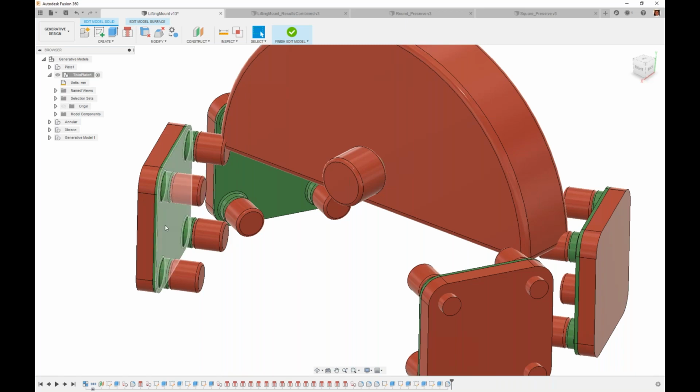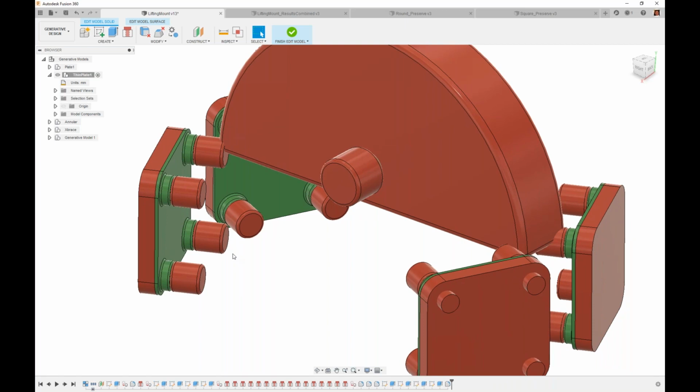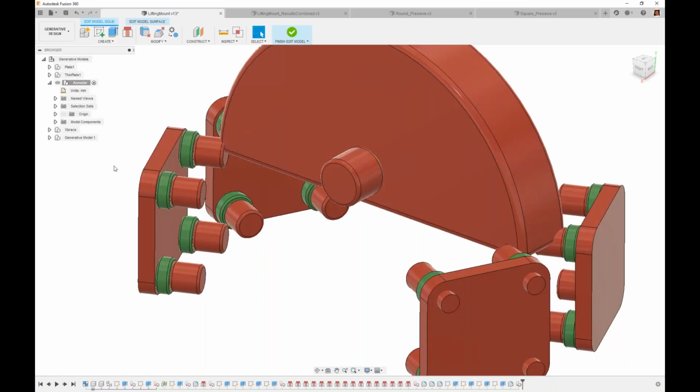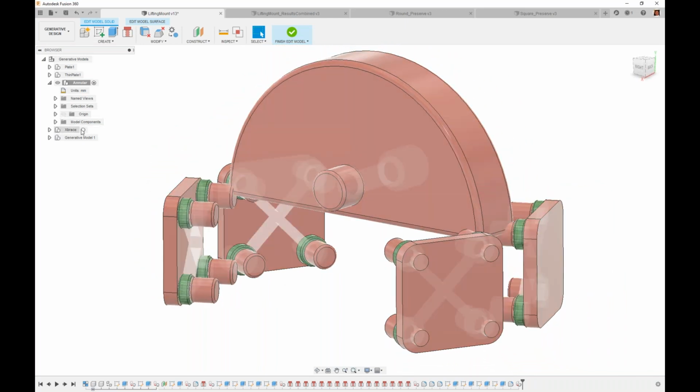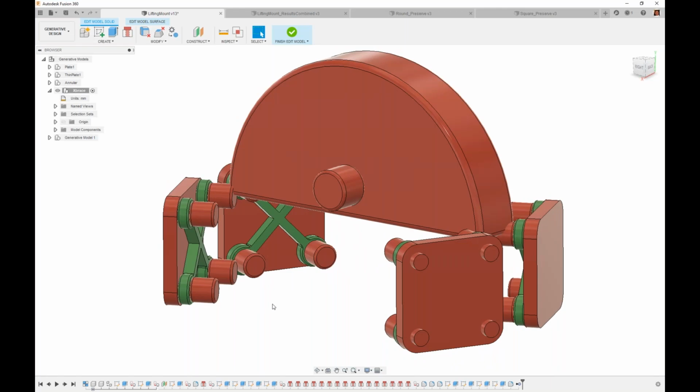So if I have a thinner plate, then I'm starting off with less mass, and so I'm already lightweighting our final geometry a little bit. Taking that even further, I said, well, what if it was just the annular regions that we were keeping? And then maybe adding a little bit of structure back and having some sort of brace between those annular regions.